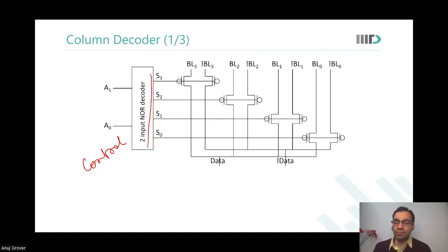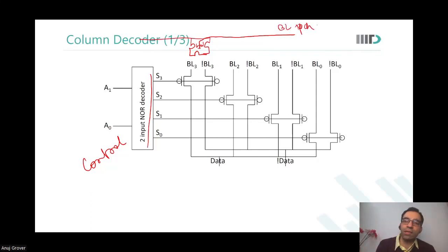What is the challenge here? Sir, you have shown the bitline precharge circuits after connecting to the decoding. Bitline precharge would be up here. Okay. So there will be a bit line precharge line going over here, something like this.